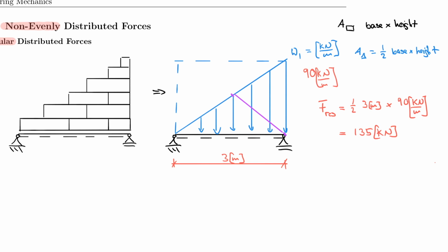So I connect that, and I can do the very same thing on the other one. And now I connect those 2 points with a straight line, and hopefully I'm doing this so correct that when I find the midpoint of the last one and connect it to the last vertex, they actually meet in the same point. And yes, it appears I did that correct. So this is technically where the lumped force would act. And this is just the geometry of it. So this is the F resultant.